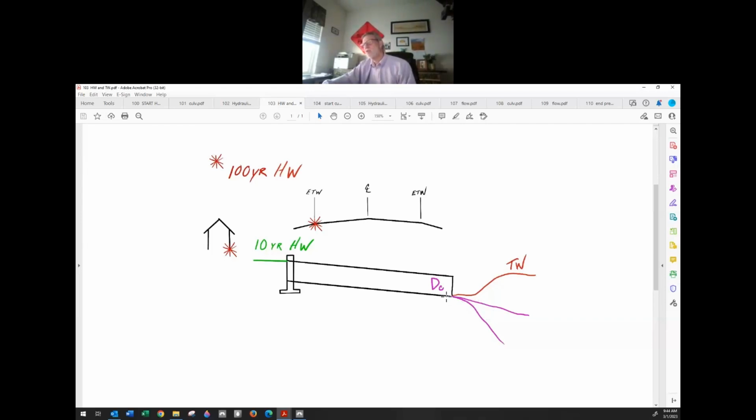That's probably the one you'll use most often. However, sometimes when the water comes out of the pipe, it has to overcome a hole. It has to fill up a hole or something like that before it can travel on and go away. And if that's the case, then the tailwater elevation is up here. And again, you want to measure the difference between the flow line elevation at the outlet and the elevation here and add those together, and that's the number you'll be looking for.